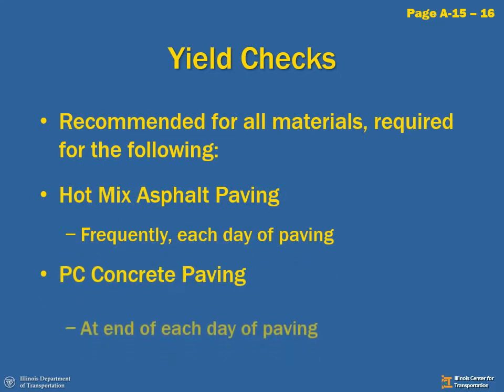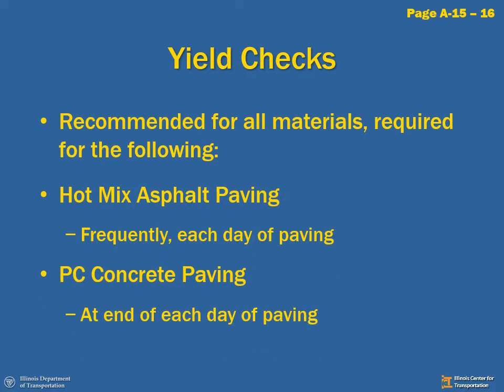Yield checks help us determine if we are getting a thickness or a volume that we require based on theoretical calculations. Yield checks are recommended for all materials. However, they are absolutely required for two items: hot mix asphalt paving and Portland cement concrete paving.